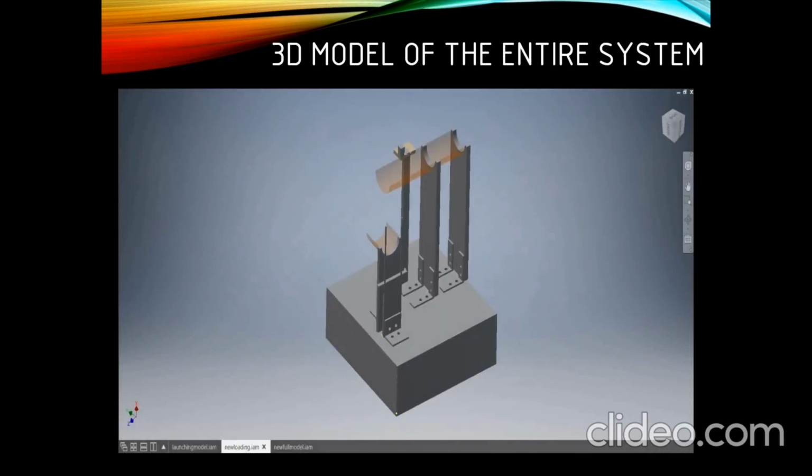This design, which we are seeing now, is an integrated design for both loading and indication part. This is the loading tray which will hold the balls which need to be launched. Its capacity will be to hold 6 balls. This here is the indication part. It consists of the IR sensor and also there is a servo here. This tray will hold the balls just before launching.